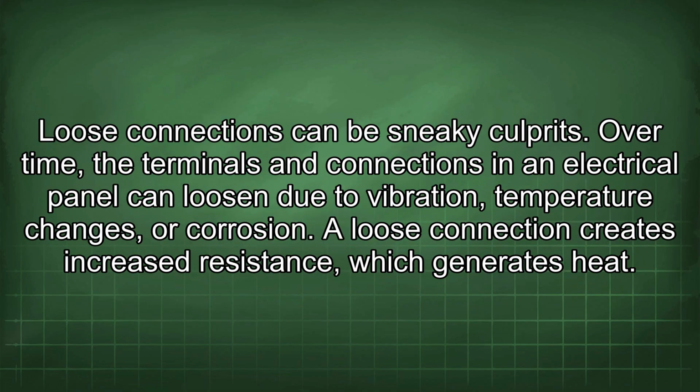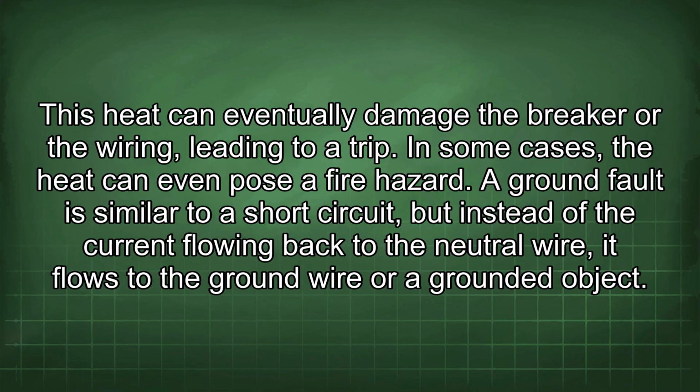Loose connections can be sneaky culprits. Over time, the terminals and connections in an electrical panel can loosen due to vibration, temperature changes, or corrosion. A loose connection creates increased resistance, which generates heat. This heat can eventually damage the breaker or the wiring, leading to a trip. In some cases, the heat can even pose a fire hazard.